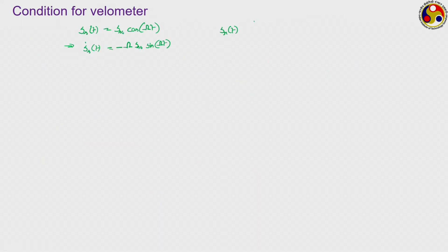If I write it again, we have r square into S_s0 into root over of (1 minus r square) whole square plus (2 zeta r) whole square, into cos of (omega t plus phi). So, this was the resultant displacement. Now, if we differentiate it with respect to time, we get the resultant velocity.